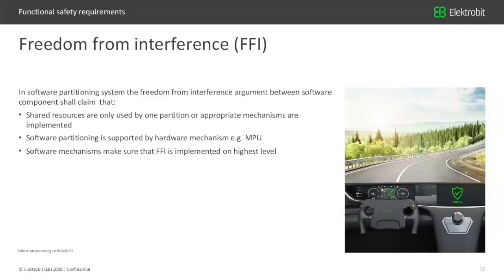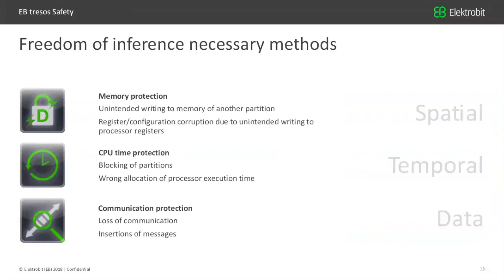Okay. That brings us to the three disciplines where I can apply freedom from interference. There we have the spatial domain, where memory protection comes into play. Here I really have a memory separation to prevent unintended writing to a system which needs to be protected. I have the temporal domain, which is basically my CPU time protection.